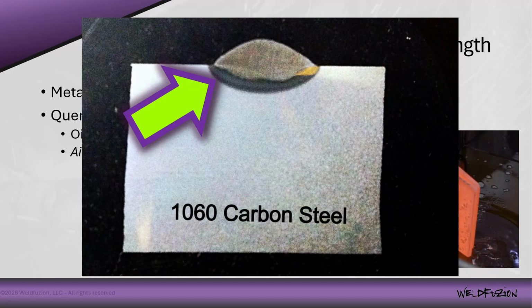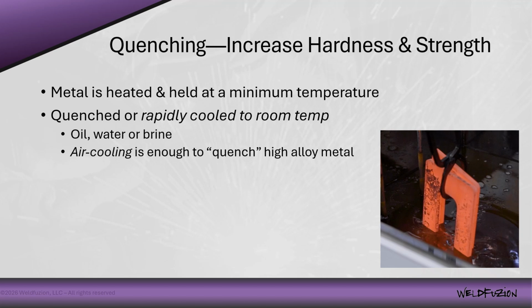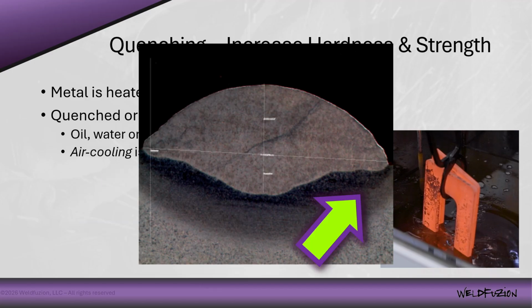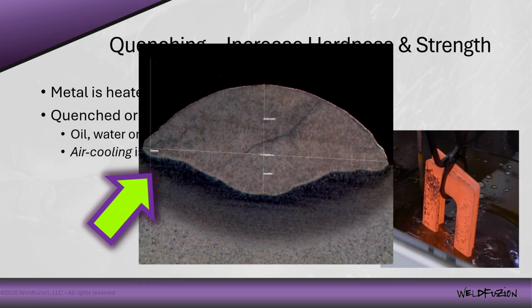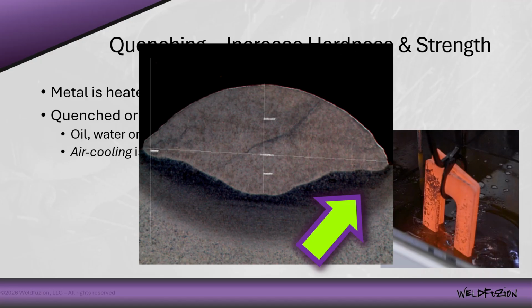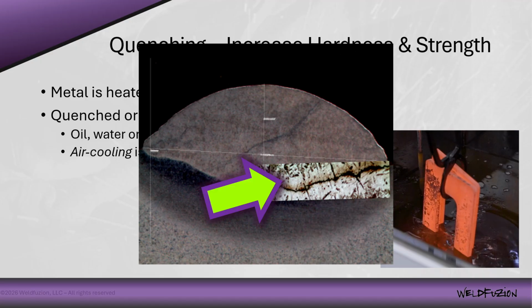Okay, so rapid cooling after welding creates the perfect scenario to create this hard, brittle, heat affected zone that can crack under the stress of heating and cooling. And that's actually what happens, right? That layer forms, and as the material heats and cools with welding, it expands and contracts. That area has nil ductility, which means when it gets pulled on or pushed on, it's not going to move, and instead it's going to crack in that area. Right? That is the whole mechanism behind underbead cracking.